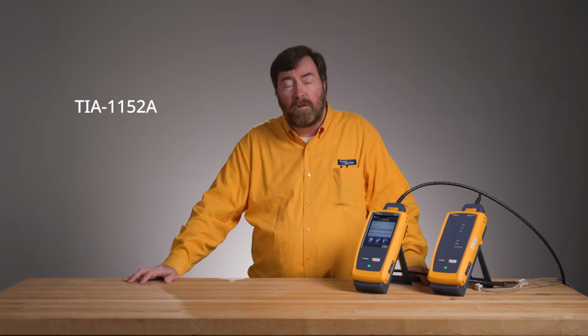Let's be quick. Now, because we have changed the component standard, it doesn't mean we need to change the tester standard. The tester standard is, of course, the TIA 1152, which is still on the A revision, but we've made an update in the current 6.13 firmware for Versiv, taking into account this adjustment for the resistance measurements.